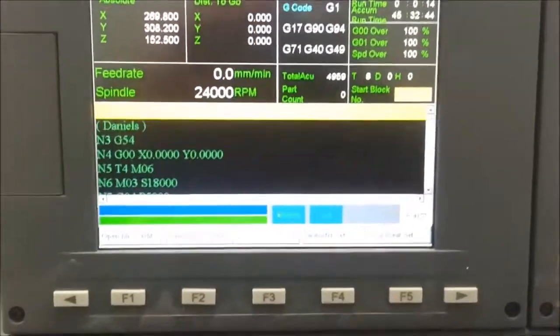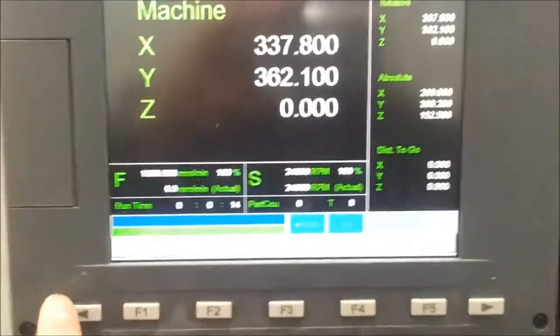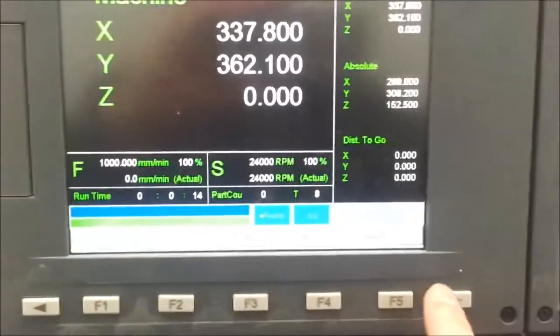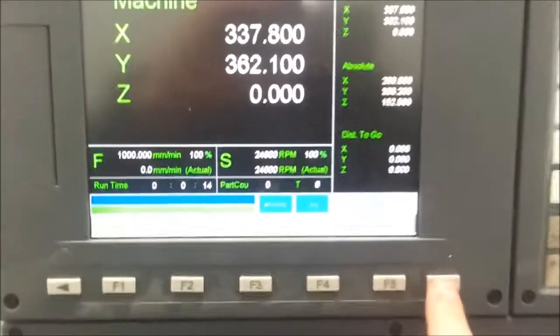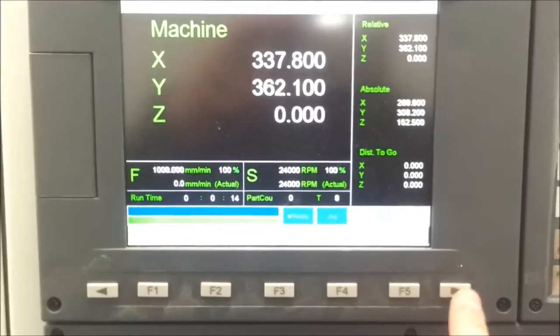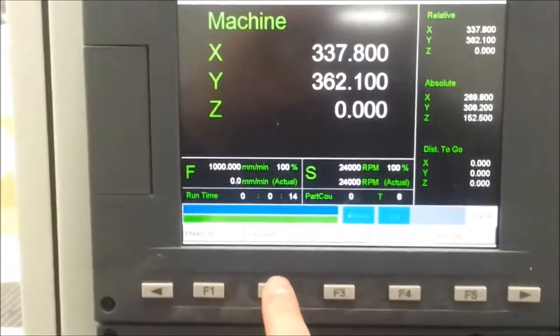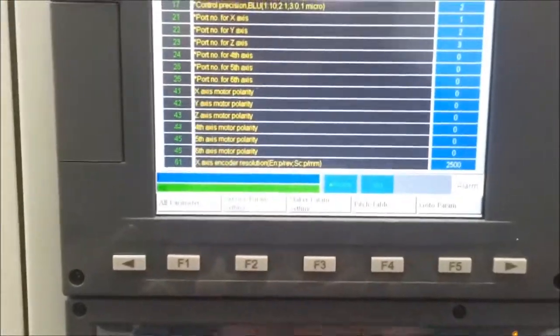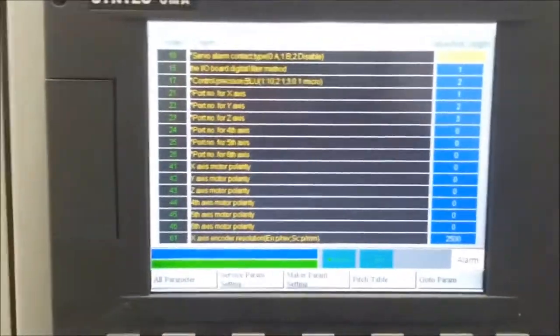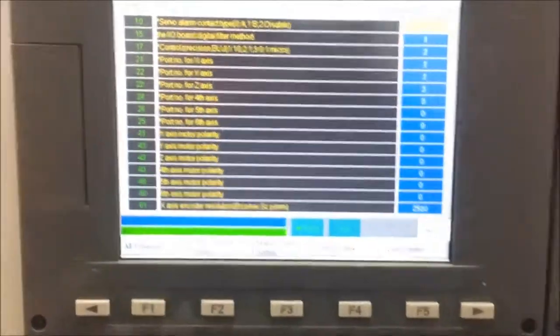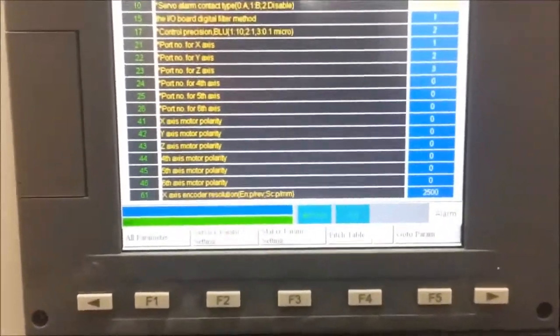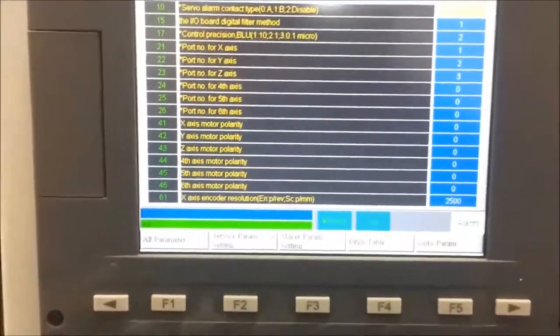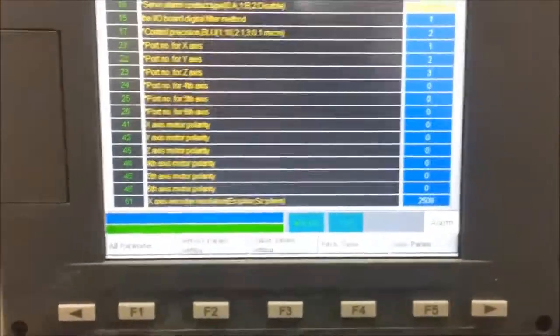Now this was fairly confusingly explained in the manual, and the best way to show you is you come out of here into the main screen and then flick across to the area that says parameter, which on this is F2 after you've moved across, and it gives you a list of all the parameters. Now it's fairly confusing, but I've been through the majority of the parameters, and the parameter that references the auto tool heights table is parameter 3411.